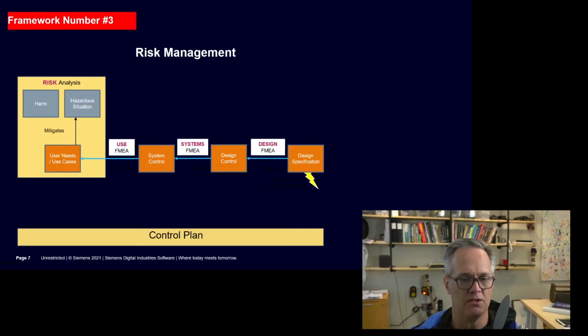Okay, so now we're going to go to the design failure mode analysis. The design failure mode analysis then processes the design control, which is restricting the migration of harmful bacteria into the device through the sterile barrier bag. And now the design specifications might be something like the sterile barrier bag will be constructed from Tyvek, or the sterile barrier bag will have a 3/8 inch thermal seal.